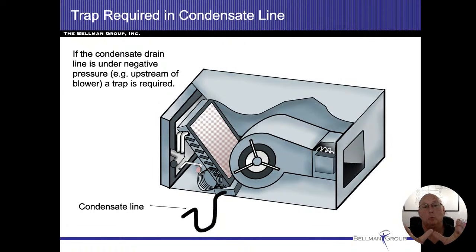Now, normal flow of air, we're never going to put our air conditioning coil before our gas forced air heat exchanger. All right, that just doesn't happen. In this drawing, they're showing this as an electric furnace. All right, so you can see the electric coils on the right side, then the blower fan, and then we have our slab coil before that. So the air is flowing from left to right.